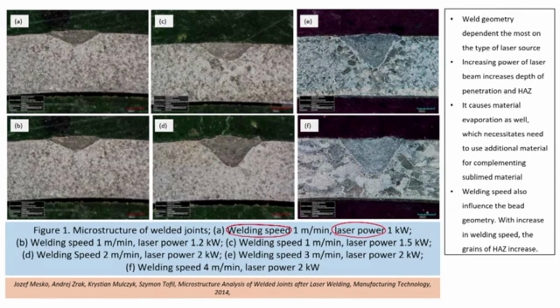The first optical micrograph is a cross-sectional cut of a laser welded specimen. So, here you can see the formation of the laser bead. This dark grey color is showing the laser bead, and this is the workpiece or the specimen.